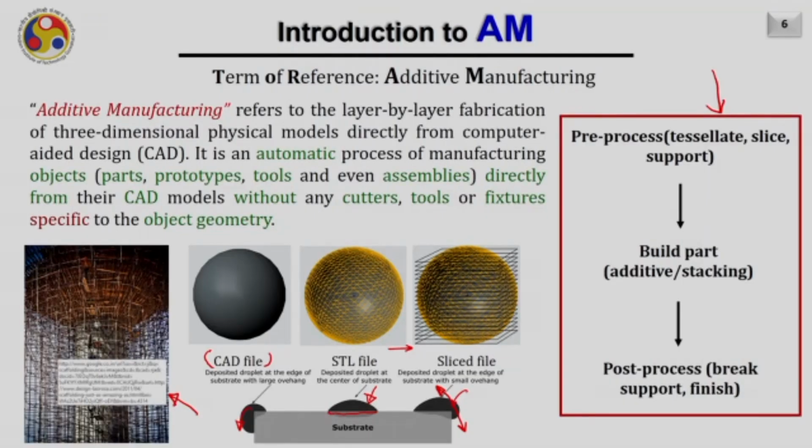Support mechanism is nothing but, you can extend this analogy from this image where a large overhang is realized by scaffolding. Later on the scaffoldings are removed when the part gets cured. It is an example of a big water tank. In a very similar fashion, in 3D printing also, when you are going to realize an overhanging feature, you need some support mechanism over here.